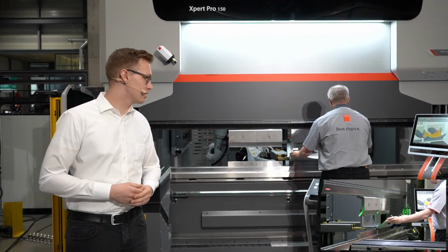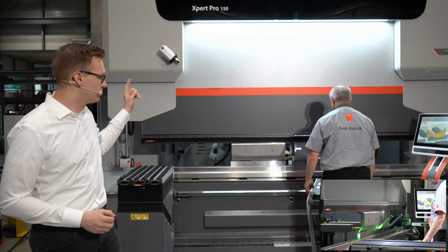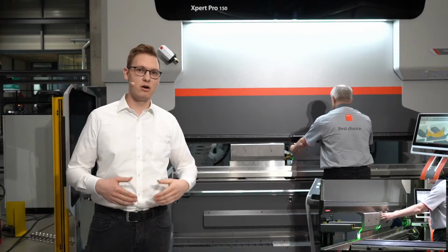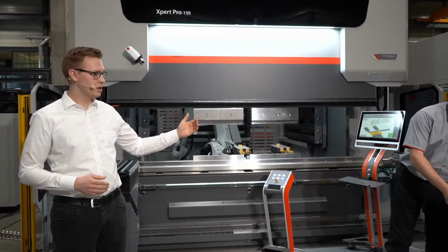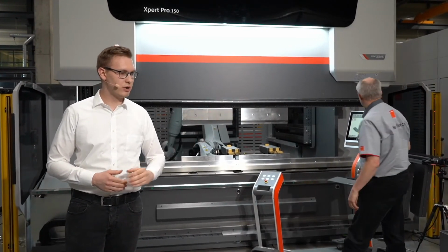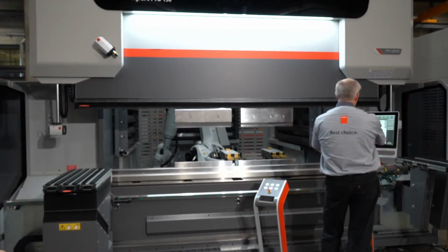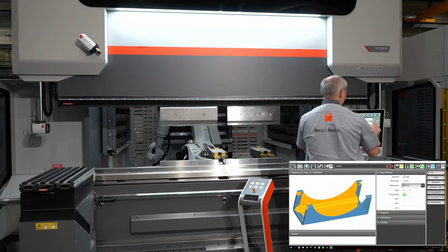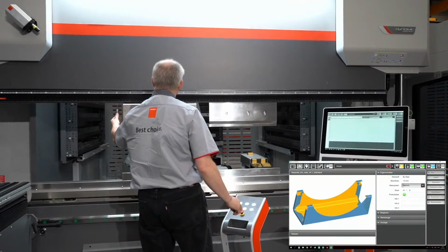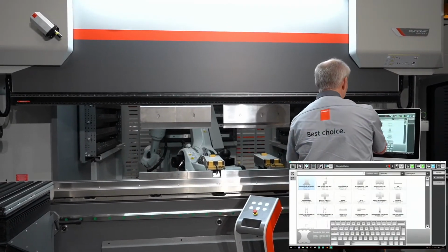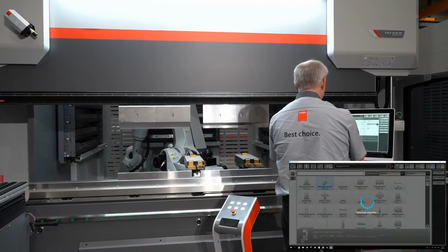And the great thing about our tool changer is it is also very flexible. We can store up to 52 meters of tools in our tool shelves in our tool changer. And right now, Thomas can bring the batches he bends to the next process area. In this time, the tool changer will change the tools automatically, and this will go really easy. So we are more efficient, we are more flexible, and of course, our operator does not have to handle up to 1 ton of tools a day manually.